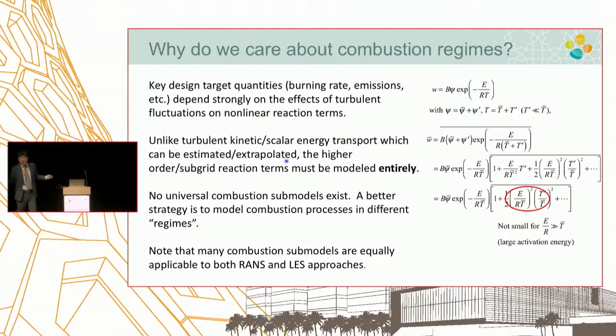Essentially, in general turbulence modeling of a turbulent flow field, all the small scales do is usually drain the kinetic energy. That's the picture of the Kolmogorov scale. So that is fine. I can ignore that, and I can easily approximate it based on good knowledge of the large-scale motion. Unfortunately, combustion is totally different.